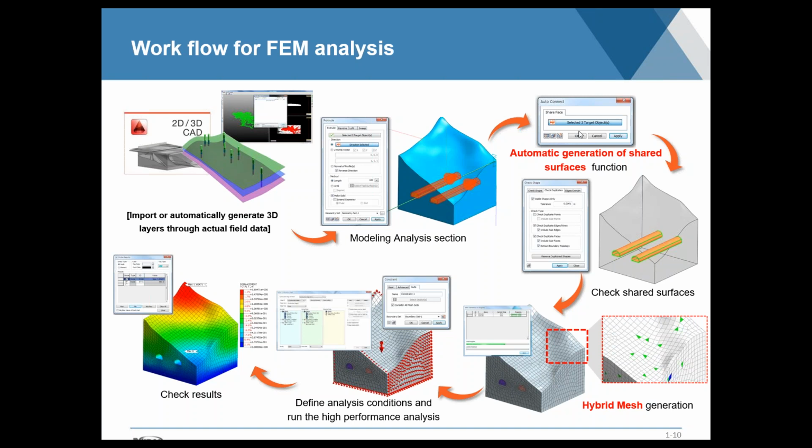We have a series of specific tools at every step of the process that verify that geometries are being properly represented and connected. It's easy to mesh, as well as verify the quality of the mesh. Easy to then, once you have the mesh, apply the boundary conditions and the loads, and then set up the analysis case to see the results. So we'll go through this whole process in an example of a simple tunnel.